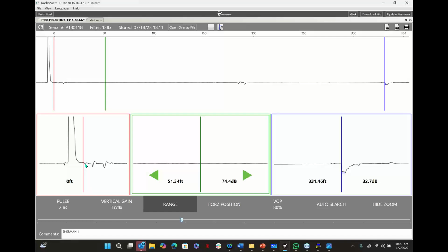So as I get connected, and this is what I'm seeing live, of course, I uploaded this to my device, the first thing I see are these two obvious humps over here at about 184 feet. So I asked them about that, and they said, yeah, that's a block splice. So we know about that, and we know that's not what's causing our problem.